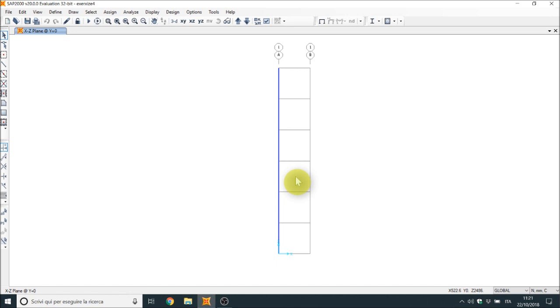Yeah, in Consteel you can do automatically this kind of implementation. You can say, give a global drift to my frame of phi equal to some values, and give an initial drift to my beam of an initial value. You can do automatically. In SAP you have to design curved beam and displace the deformed frame. So Eurocode allows you to insert equivalent forces.